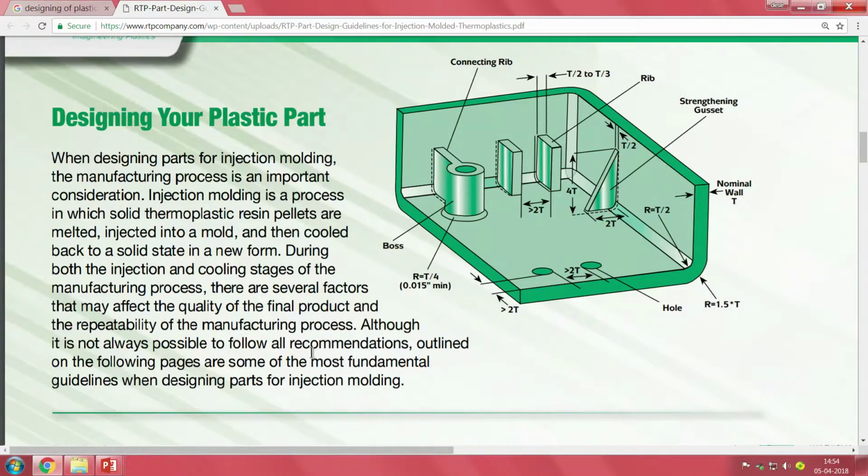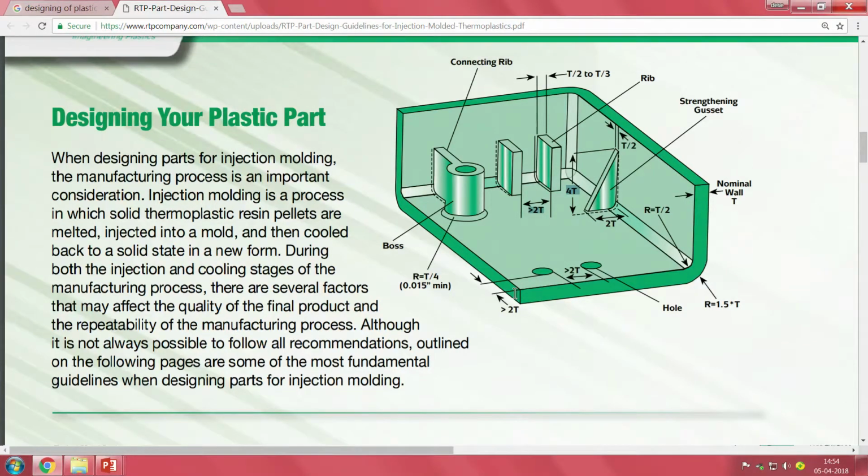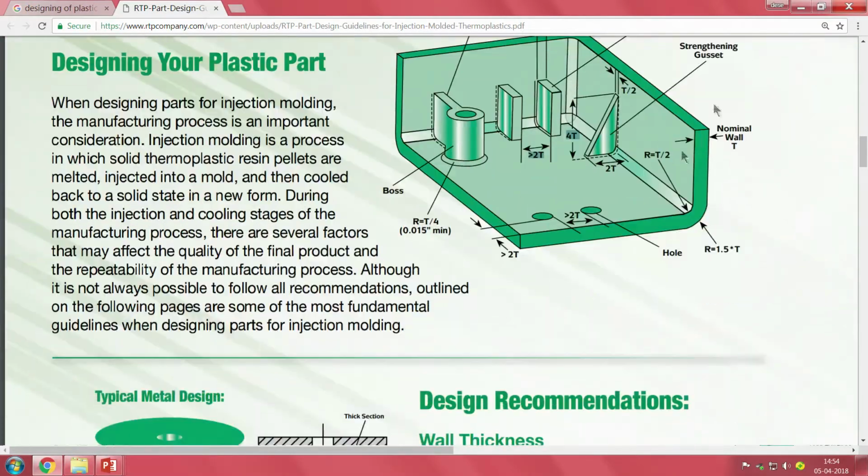So, one of the typical things is, imagine some material is being injected in this corner, and the material has a tendency to flow in both directions. It will come and join at this place and may end up with what is called a cold shut. By the time they come here, if you make it too warm or too hot, there are some problems. If you make it cold, you may end up with two surfaces joining together with a visible joining line, which is a possible problem.